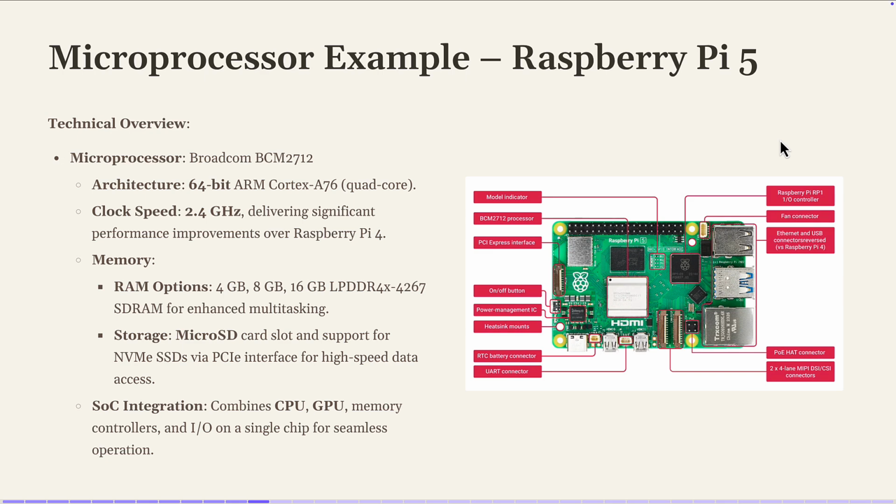USB can only provide, it was a Raspberry Pi 3 at that time. I think it provides only 5 volts. And the power requirement of the device was even much higher than 5 volts. So it was just failing when I wanted to connect the sensor to the board. So it's really very important when you buy a sensor you want to connect to any board to understand the power requirement. Okay, because usually this USB is going to provide you some power, and it has to be matching the power requirement of the device that you will be connecting to your embedded system.